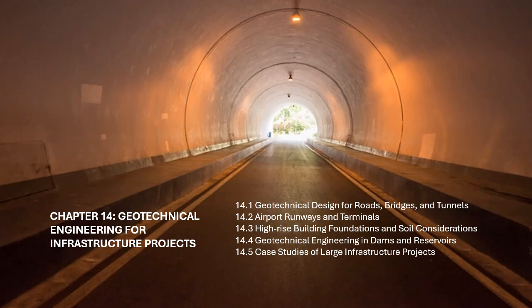Engineering solutions. Extensive geotechnical investigations were carried out prior to construction, including borehole sampling and seismic profiling to assess the soil and rock conditions. A combination of tunneling methods was used, including the tunnel boring machine (TBM) and the cut and cover method, to manage the variable ground conditions encountered along the tunnel route.